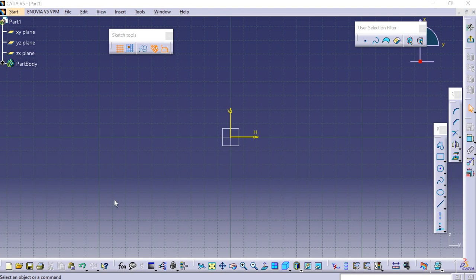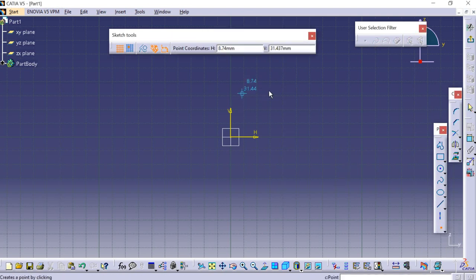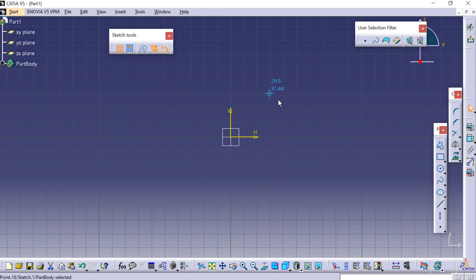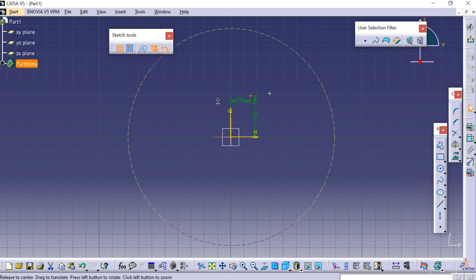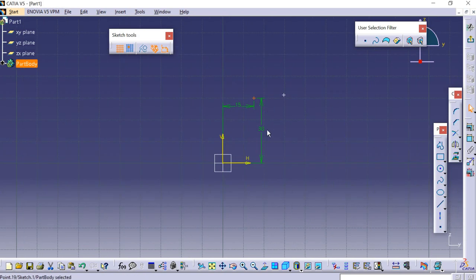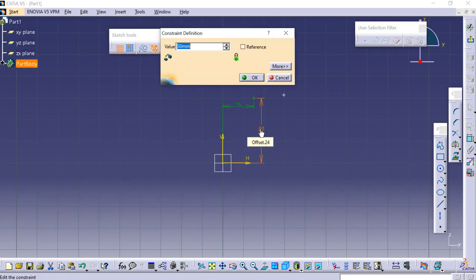Let us move on to part 6 of our basic task. So here we'll be creating a point. This option here is the point. We can either click on the grid where we want the point, or we can enter the coordinates here, 15, 30. So we can see that the point is created, which is constrained on the grid,